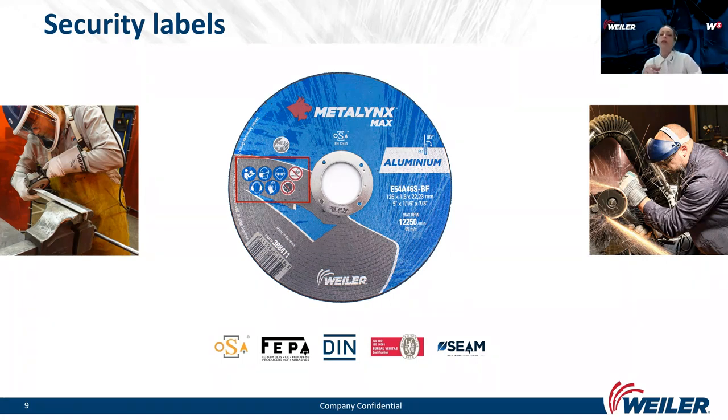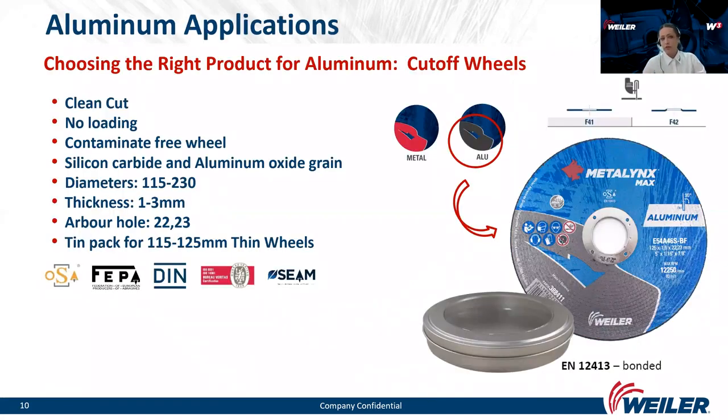So you also need to be aware of some other risks, like cross-contaminations. So don't use cutting or grinding wheels, for instance, first on aluminum and then on something rusty, because altogether this will form thermite, which is really flammable. So dangerous. For instance, aluminum oxide is used in fireworks, so I think that says enough.